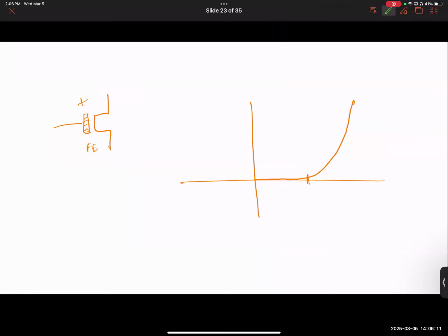When you have negative polarization, you have a different threshold voltage. Does that make sense? So with the same transistor, you could change the threshold voltage by programming the ferroelectric into different polarization states, either positive or negative. So the transistor shows you two different threshold voltages. Is that clear enough? This is the basic principle, and let me show you.